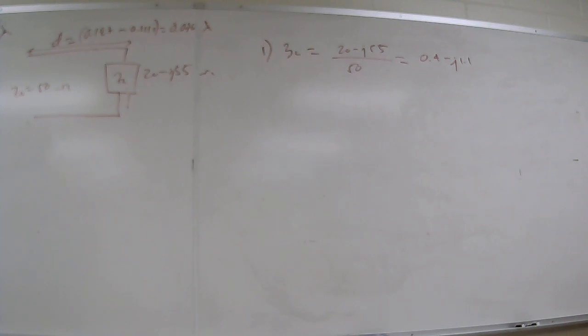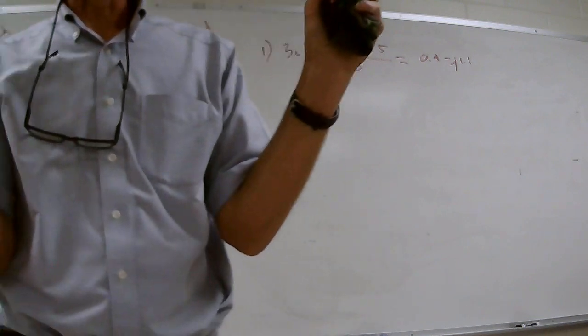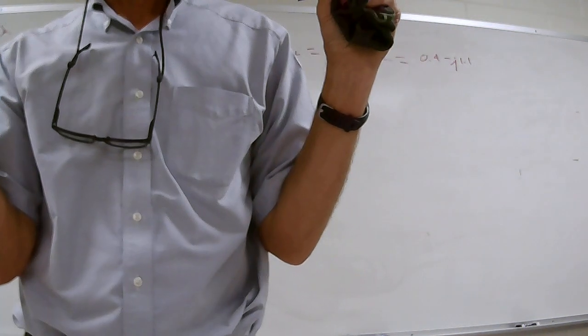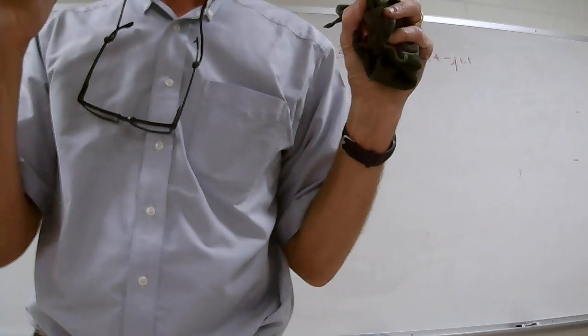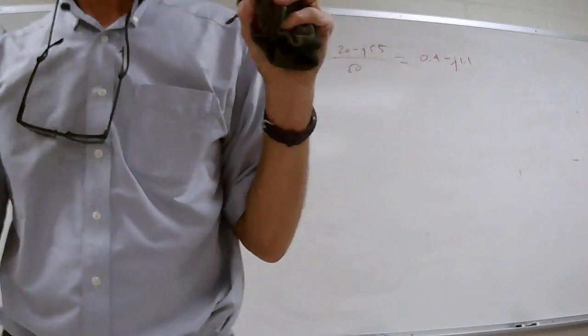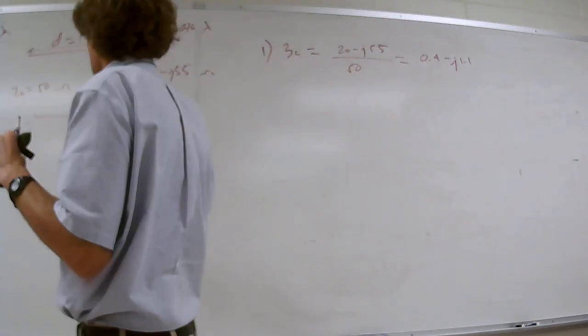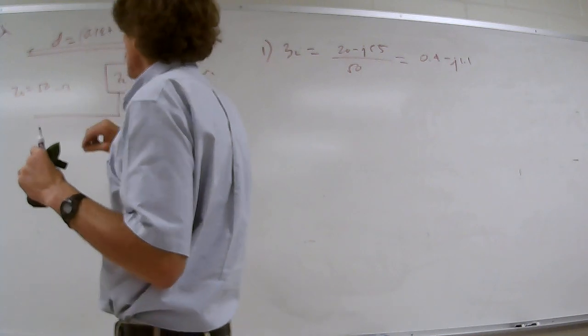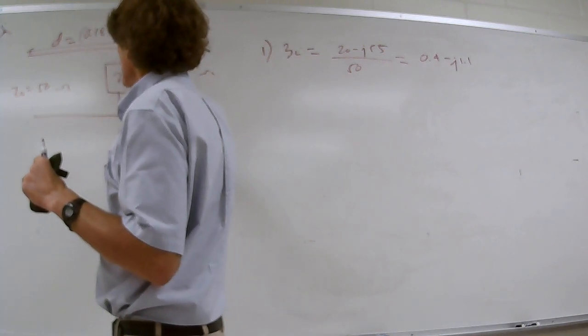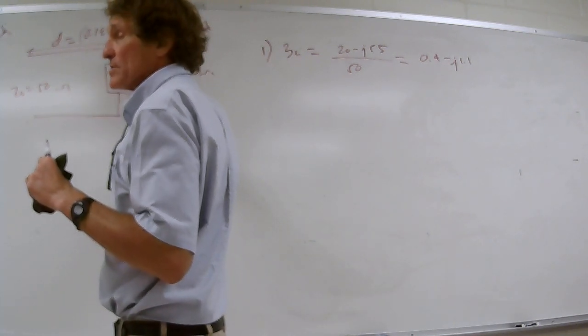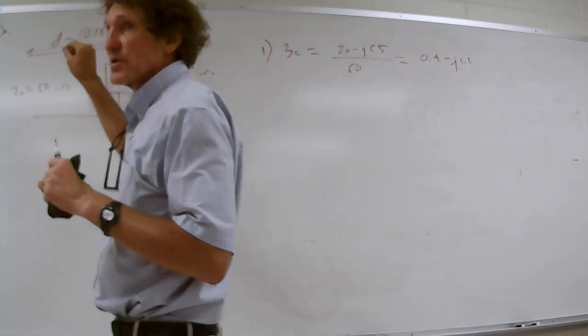Normally they say you have to be at least 1/10 of a wavelength or longer before it will act as a transmission line. You can get away with this stuff, but usually you're going to have some way of adjusting, probably putting a small capacitor in series here where we can tune it so you get a perfect match.